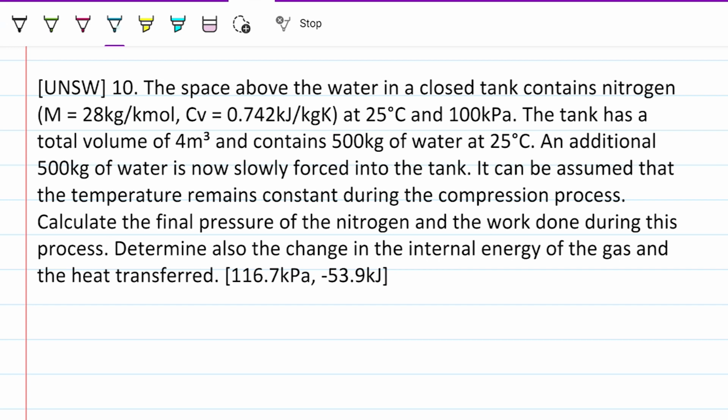So let's analyze this. The space above the water in a closed tank contains nitrogen. So the space above the water, right? Let's imagine a cup with water. The air on top of it, that's what they're talking about. But it's a closed container, so it's a cup that has a lid. Closed container is just saying we can apply our first law of thermodynamics for closed systems.